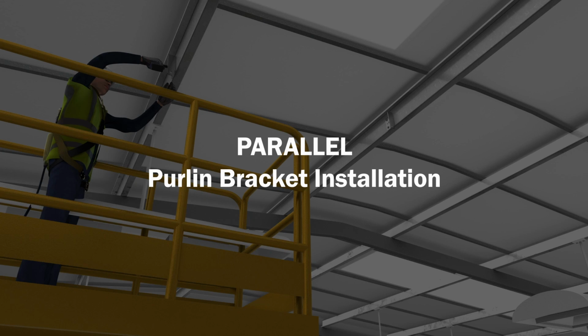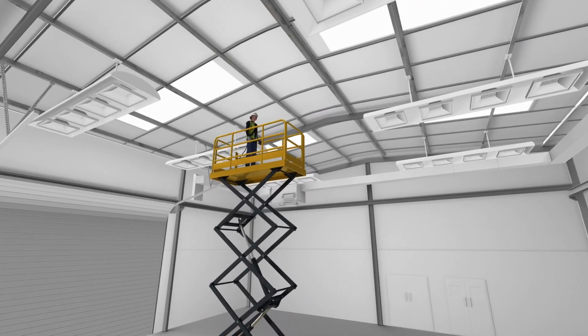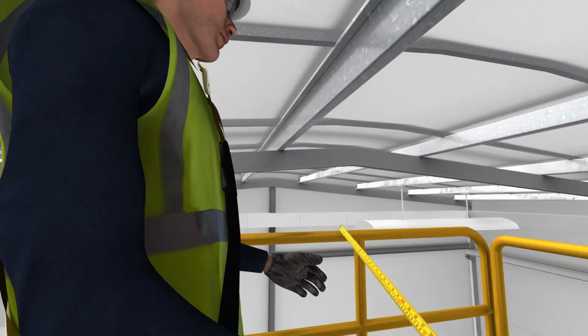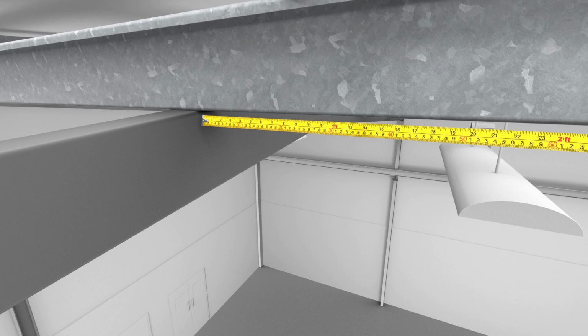Parallel purlin bracket installation. Create a datum point from a wall or a feature of the building to establish the center line for the rigid rail. A datum is a physical point or position that you decide, serving as a reference or base for the measurement of other values.